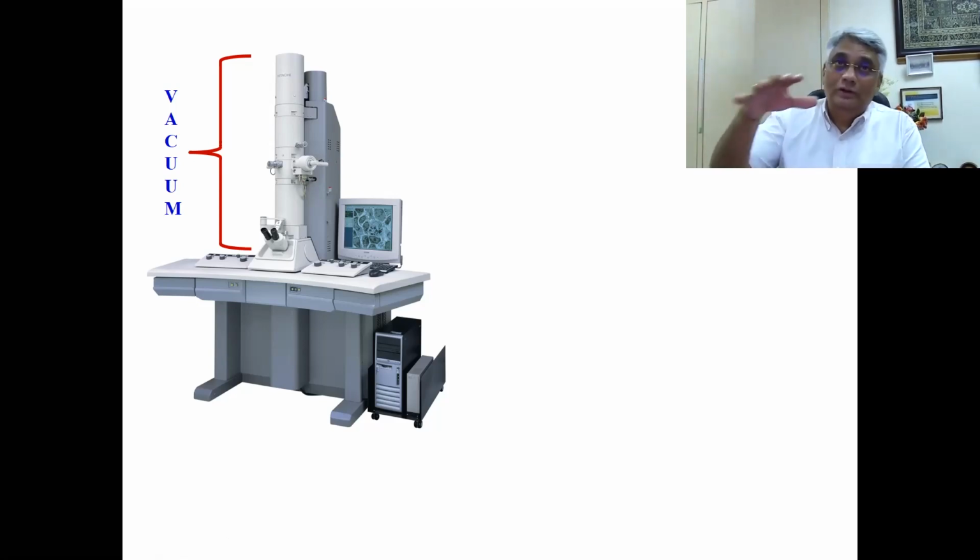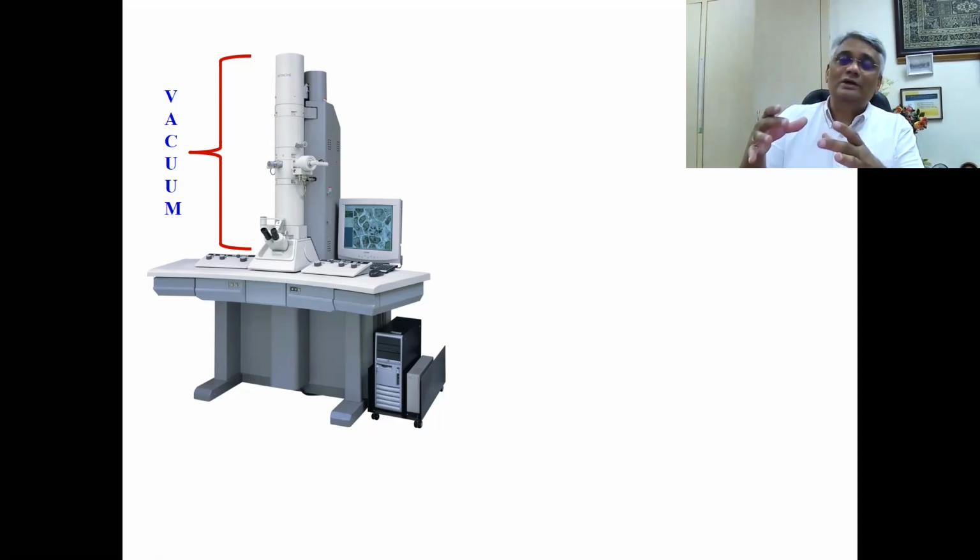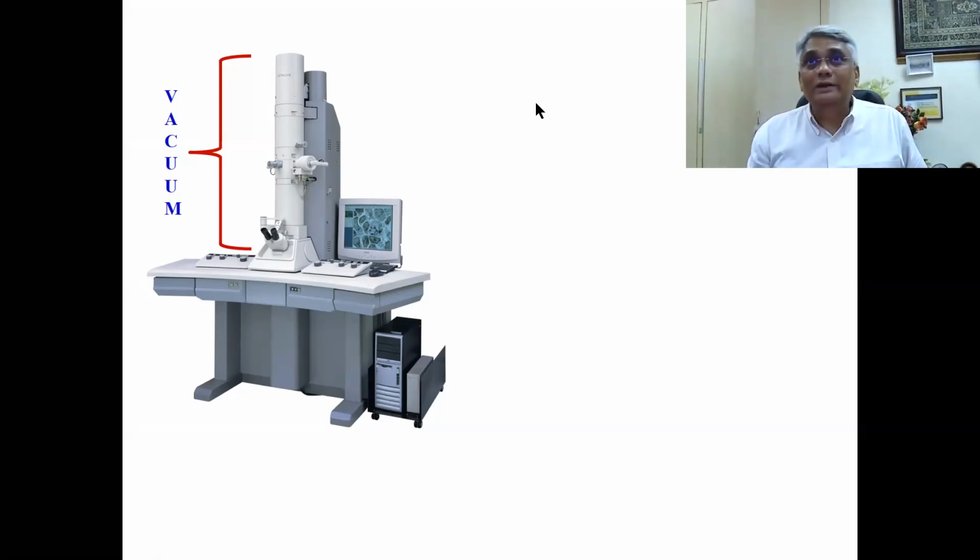I can also do wavelength dispersive X-ray spectroscopy, WDS. A lot of information. So on the area on which imaging is done, you can also map and see what are the elements present, and how are these elements distributed in a given area. Really fantastic. And the third one is the same electron beam can be used for electron diffraction, right?